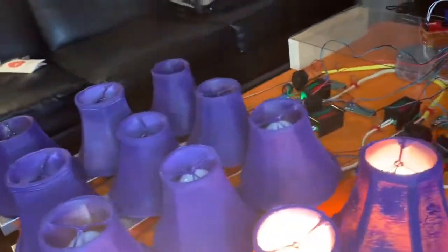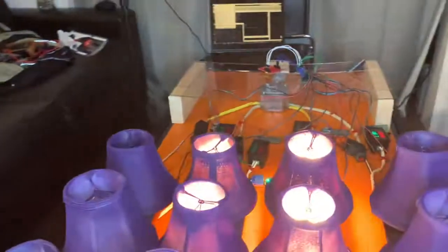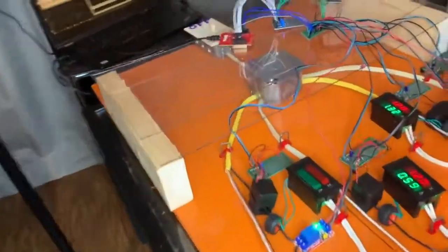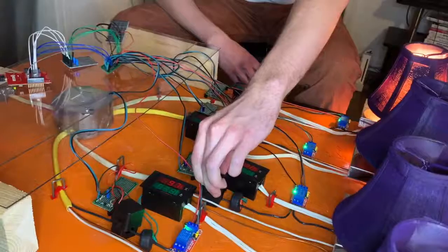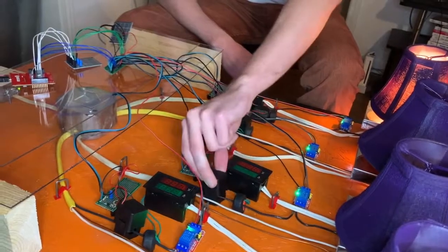So I'm going to talk a little bit about the hardware used. We started off by cannibalizing an extension cord, which allowed us to grab a power source from the wall. We put this through an electrical box and used that as a branch to branch out to 4 separate lines. These 4 lines had current transformers and inline amp and volt meters on the lines so that we could prove the concept that we were trying to create.